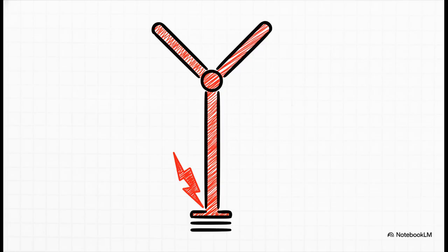Before we wrap up, though, I do need to note that this accessible neutral point in a Y system isn't just a convenient math trick. In the physical world, it's actually a critical protection decision. That neutral point provides a physical path to run a conductor straight into the earth. Neutral grounding means that if a fault occurs, dangerous currents have a safe path to flow to ground, rather than building up on the metal frames of the equipment and putting personnel in danger.